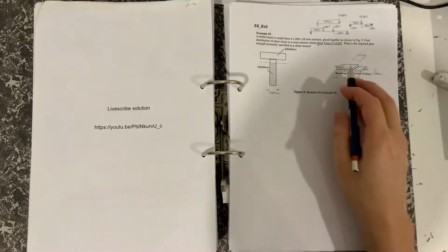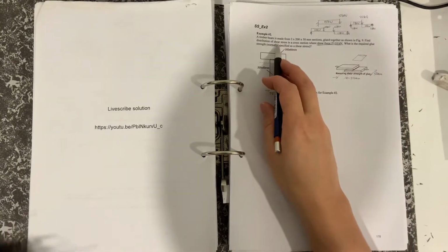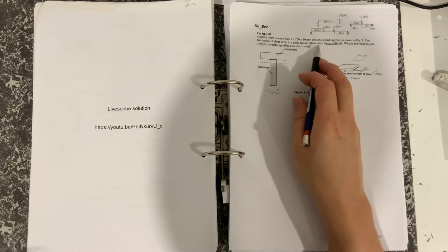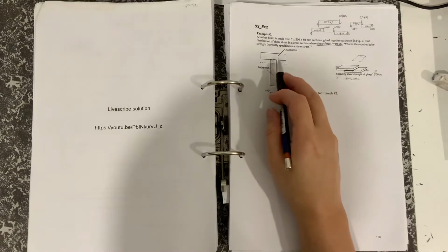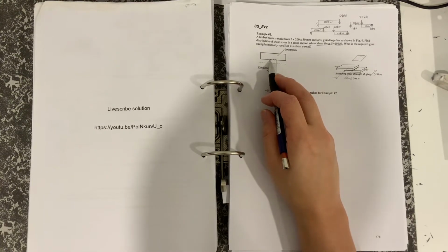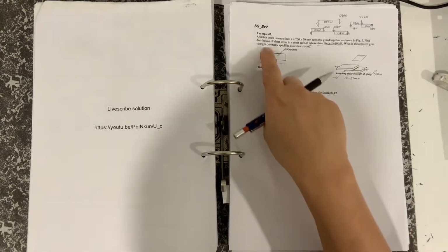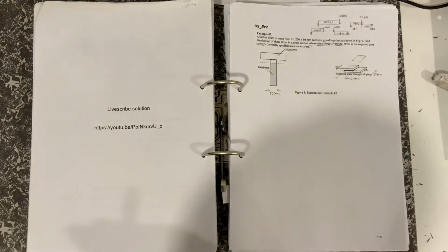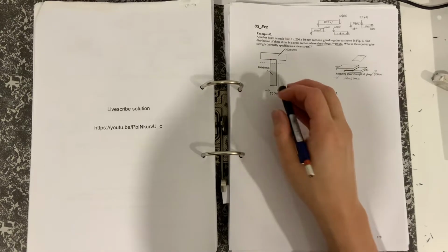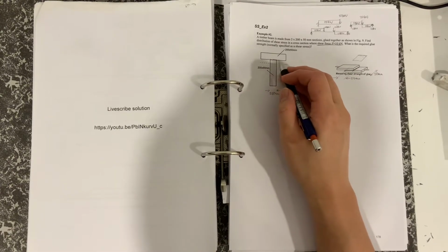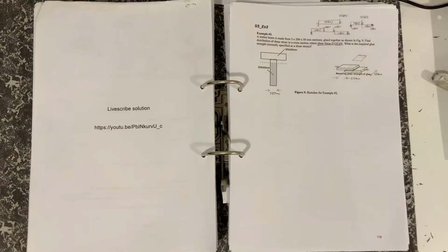So how do we find the distribution of shear stress in a cross section where the shear force is equal to 10 kilonewtons? So we're assuming that the glue is strong enough across there. So I'll just talk you through how we might do the solution. First of all, you've got this top surface, you've got that bit there. So we're going to have to be calculating the second moment of inertia.